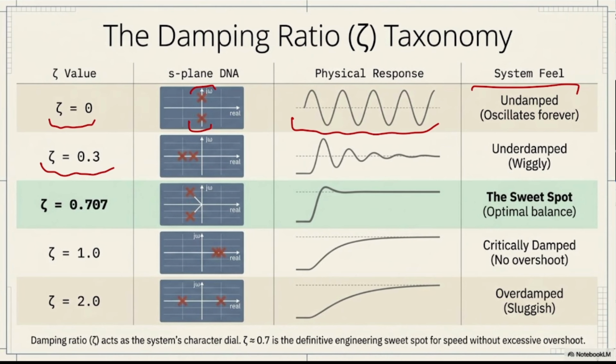Another thing that we do have is a damping of 0.3. Still it is not that big, it still is near 0, but it's not that bad. So at this point, I do have some poles, and both of those poles are going to be on the left side, but with this specific condition that I don't have much of an imaginary part. At this point, I have to consider the imaginary section. But you can see over here that I do have a little bit of oscillation. Again, remember that any oscillation that you see for the system itself is related to imaginary.